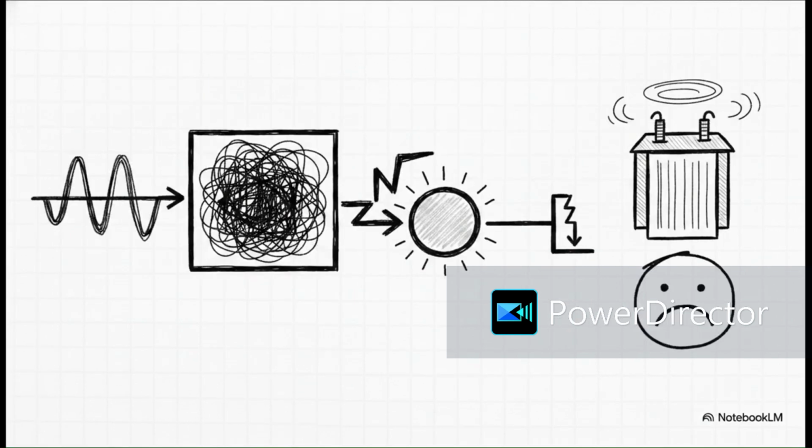So, why does a simple angle shift matter? Well, because these phase shifts cause absolute chaos for our protection scheme. That natural phase shift artificially alters the magnitude of the current on either side of the transformer. Remember our perfectly balanced weighing scale? Yeah, the relay looks at these artificially changed currents and just gets completely confused. It sees a difference, falsely pushes that phantom difference right into the operating coil, and bam! Unwanted circuit breaker trip. A perfectly healthy transformer shuts down just because of its own geometry.